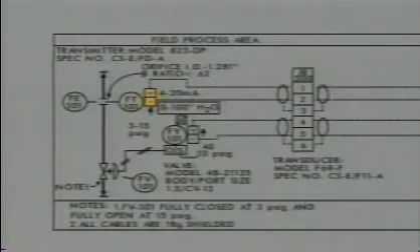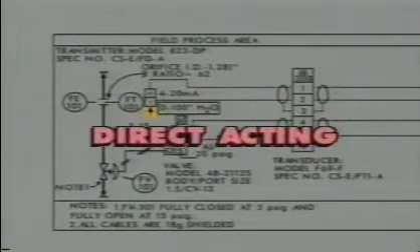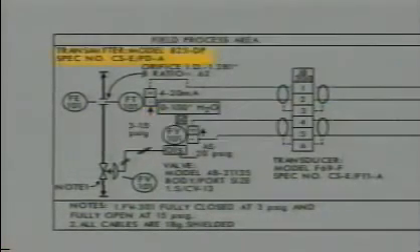The connection points at the transmitter are terminals. The positive and negative signs indicate the polarity of the terminals. This transmitter sends a 4 to 20 milliamp signal. You also see an arrow pointing up, which indicates that this transmitter is direct acting. So you know the output signal of the transmitter increases as the input to the transmitter increases. The specifications give you the model number and specification number for the transmitter.